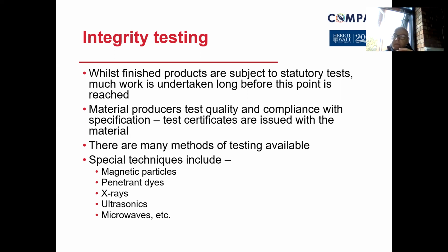The thorough examiners will do a visual inspection, and if they're not happy and they see a slight fracture or a crack on the heel of the forks, they might then use these non-destructive techniques to see whether it's acceptable or not. And if they're still not happy with that, then they'll put it under load.